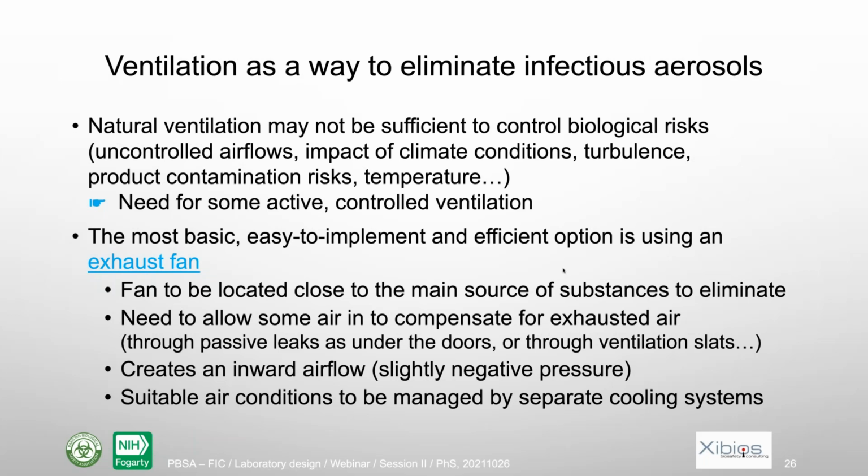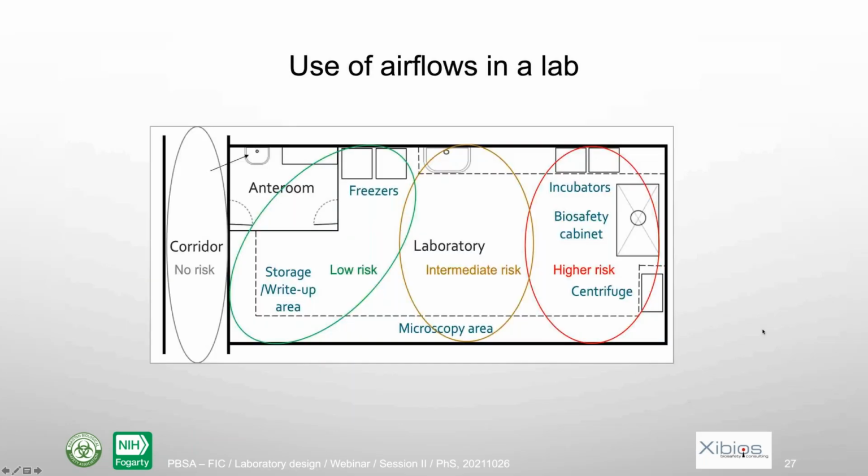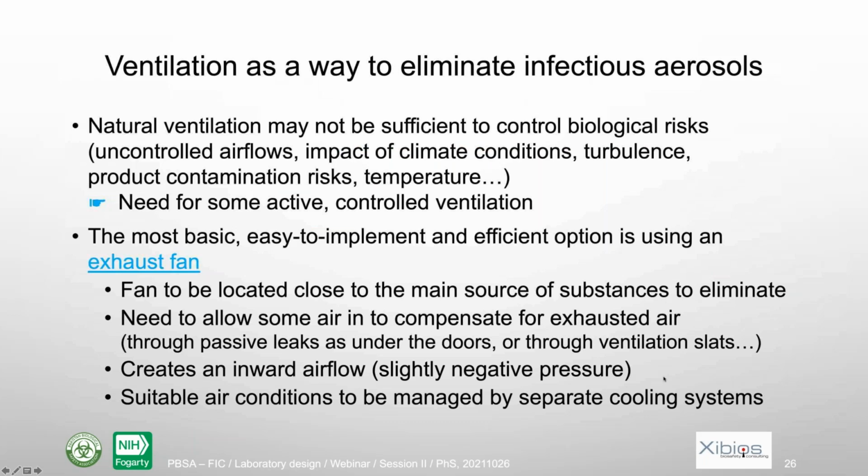Also, if you take some air away from the lab, you will create a negative pressure in the lab. That means that some air needs to enter that lab to compensate. Most of the time, with most labs, you don't have to worry about that because there are some leaks in different places, like under the door, close to the windows, and so on. But if you have a lab which is too airtight, in that case, you might need some ventilation slats. That means some grills that will allow the air in.